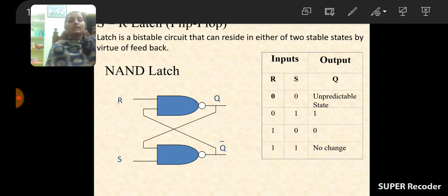So to prevent the latches from that overspeed or delay, we are using the clock pulse. By application of the clock pulse, if the clock pulse is not there, even though the inputs are present, the output is not produced. After receiving the signal from the previous stage only, the output is produced. So that is the main theme of the clock pulse.